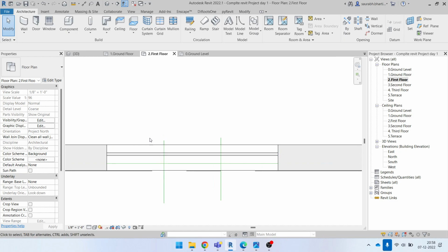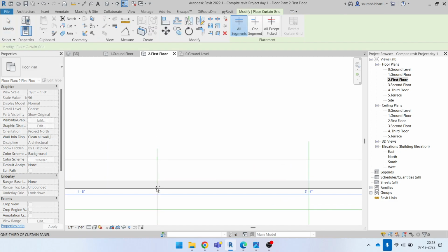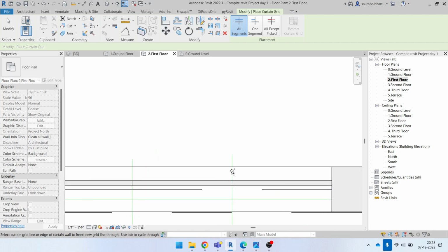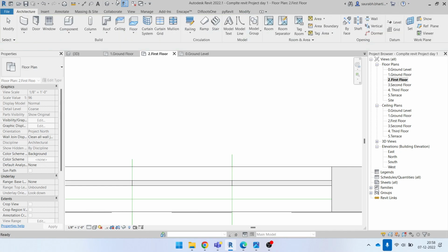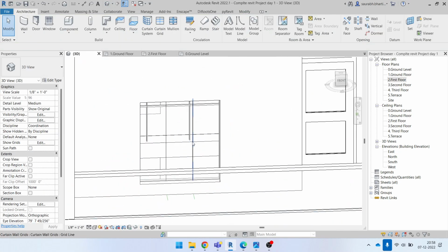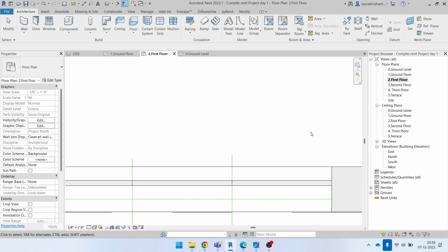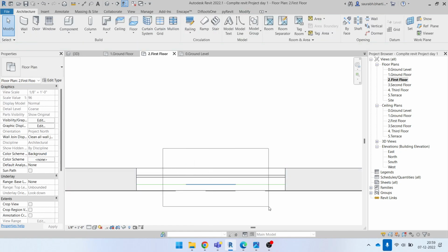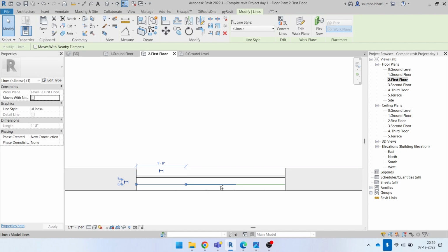Okay, so if I go to the cut and grid here, now you can cut this glass into the number of segments. So first segment is over here, second segment is over here. I think we made a cut here. So if we go to 3D view, now you can see there's a 1 2 3 cut. Okay, that's one thing that you can do. The other thing that we have is, I'm just undoing this. Okay, I'm just deleting this. I'm selecting it and pressing the delete button. So we don't have any cut here, we don't want this line here.